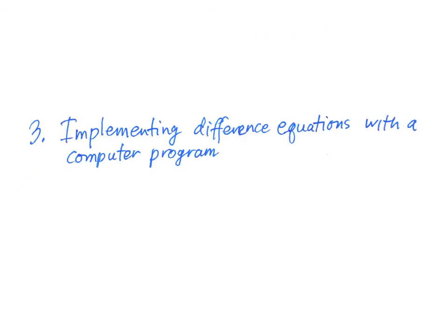Well, it's possible to design hardware that's dedicated to implement those difference equations. Just implement that network diagram directly. For delay units, you just have a shift register that stores values and shifts them on with each clock pulse. In a computer program, there is no dedicated hardware. We're using instructions to a computer that may be reprogrammed in order to process a list of numbers.